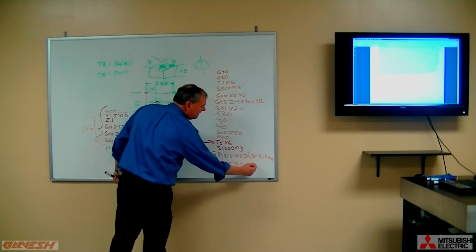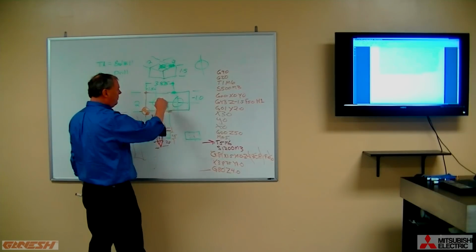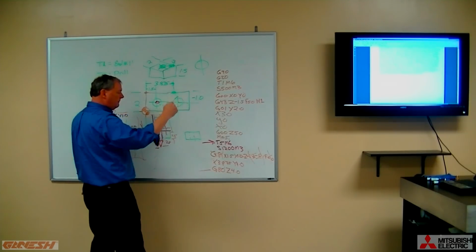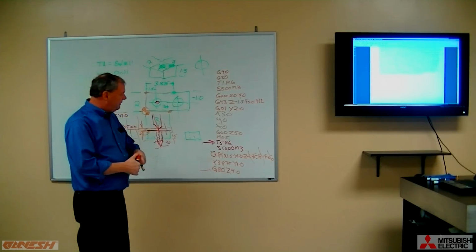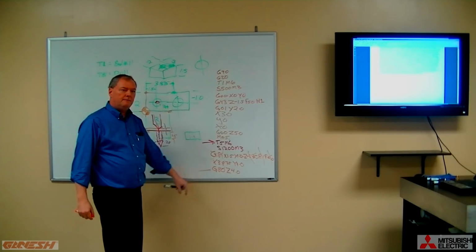I don't have to repeat this stuff because it's already been set up. So it's going to go right over to the next hole, drill down and come back out again. And it's going to do that for every set of X and Y coordinates until it sees a G80.